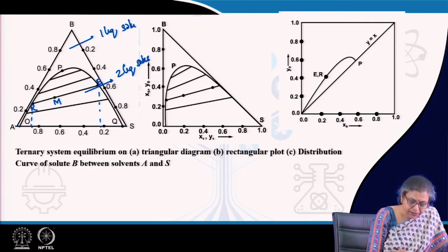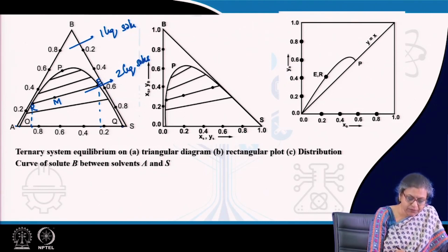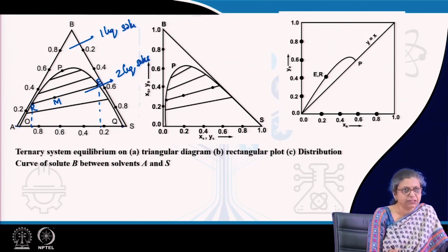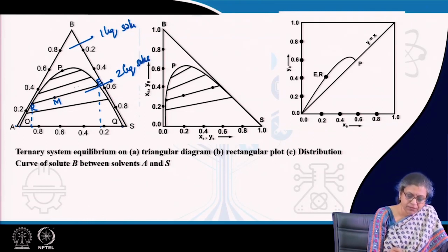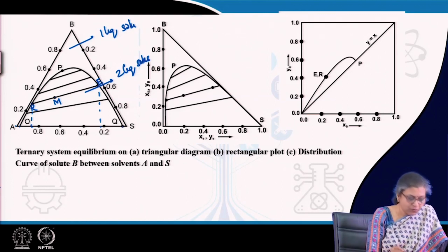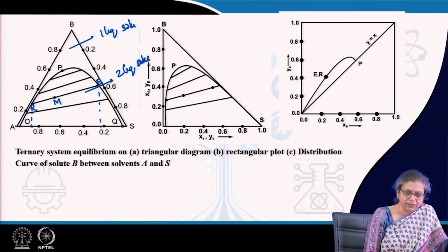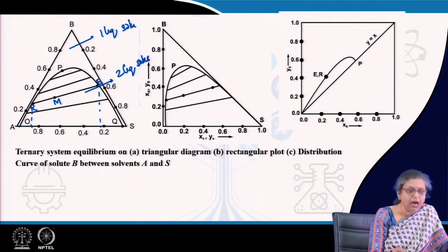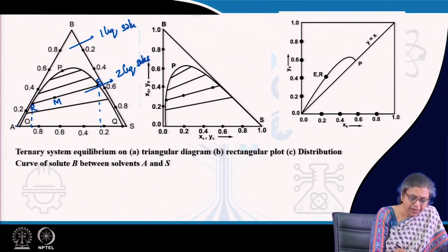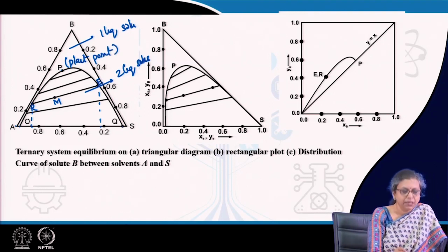So, this particular line, which represents the raffinate and extract composition in equilibrium to the overall composition of the liquid mixture, is known as a tie line. And you will observe that in this particular case these tie lines are not parallel. Usually they slope in an upward direction and they gradually become smaller and smaller till finally it reduces to a point. This point is known as the plait point. Beyond this is the limiting condition for this immiscible zone.